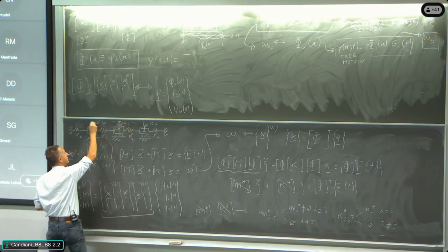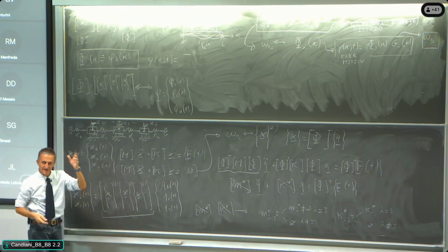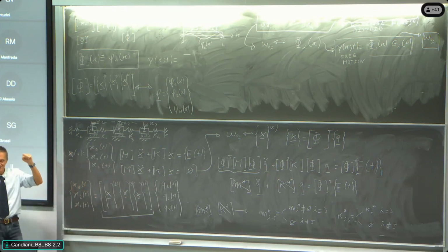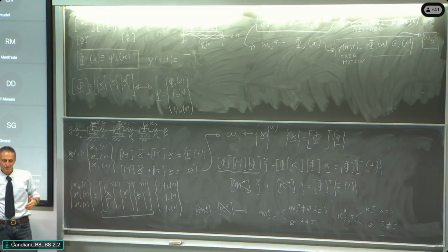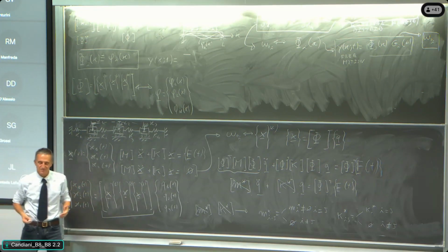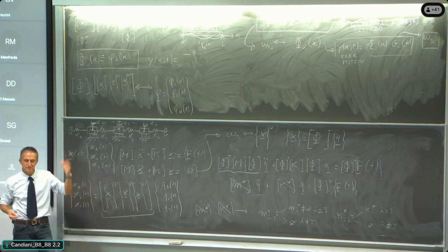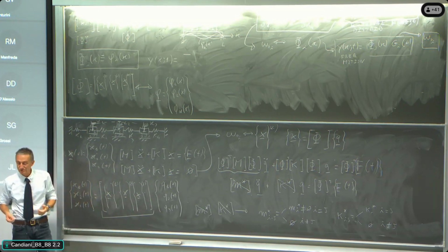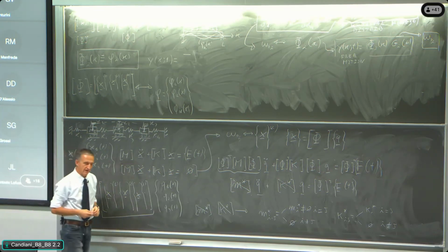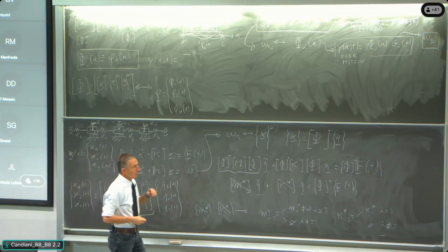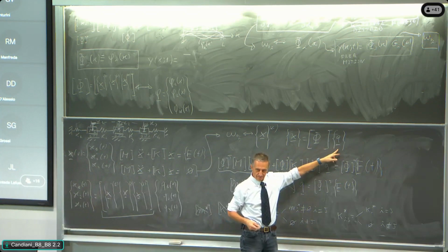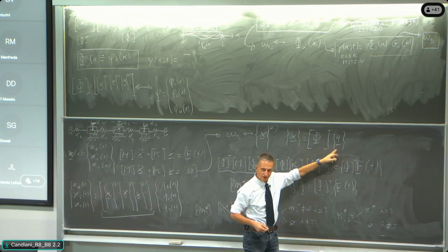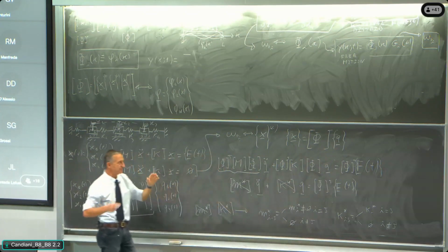This one is positive, and one of those could be 1 because we are normalizing. The modal shapes must be normalized. It is also possible not to normalize, but it is much more useful. Almost always we normalize the modal shapes to 1: the maximum is 1 and the others are less. Why? Because it is very useful. When I am reading the amount of movement through the principal coordinate q, when this is 1, it means the largest is moving 1.